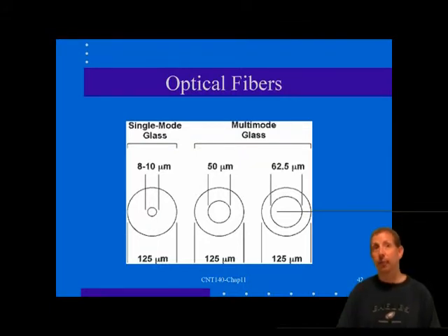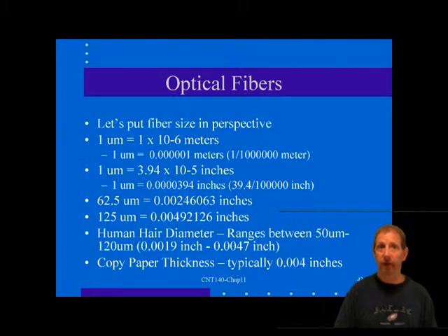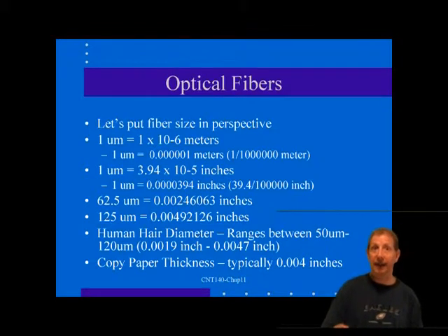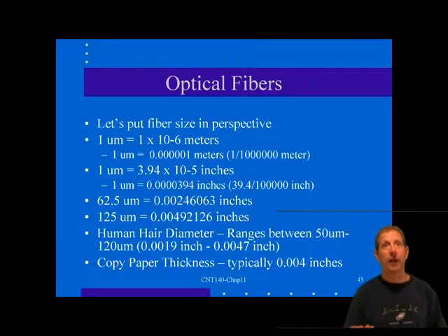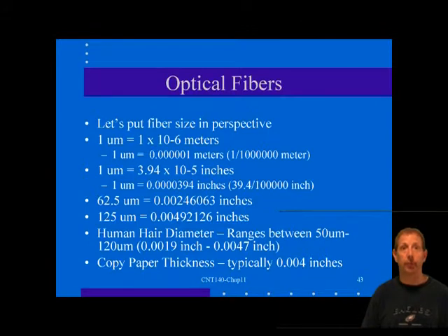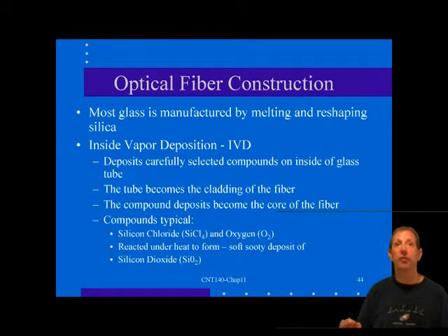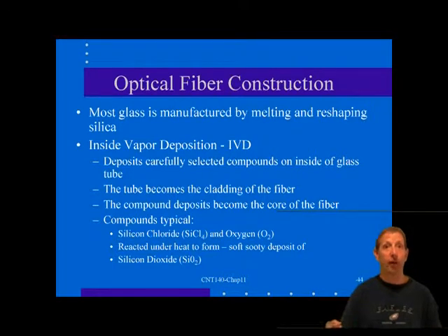Now, if we look at some fiber optic cable configurations, the cables are available in a wide variety of physical constructions. Fiber cable can be anything from simple 2-fiber zip cord used for jumpers to 144 fiber cable, often layered in rows of 12 for intercity transmissions.